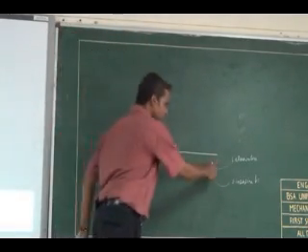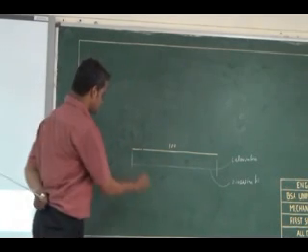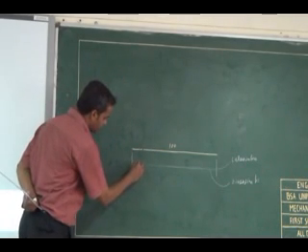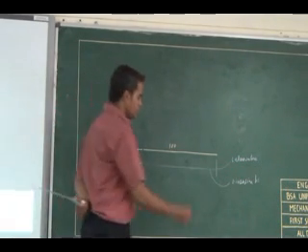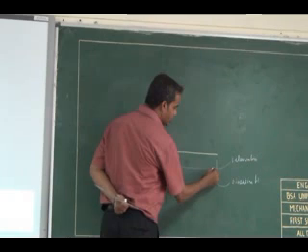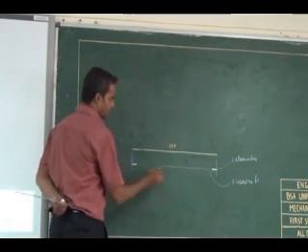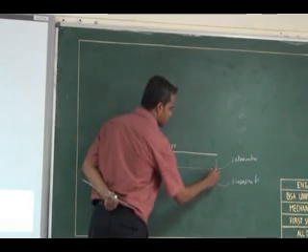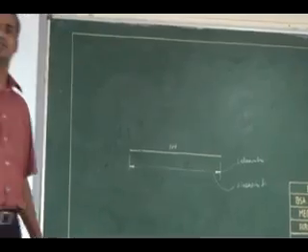So which is my extension line? This is. So the arrowhead I will place on the dimension line. See here, I will place the arrowhead here pointing towards the extension line. The arrowhead I am drawing is pointing towards the extension line. Is it clear? Right.